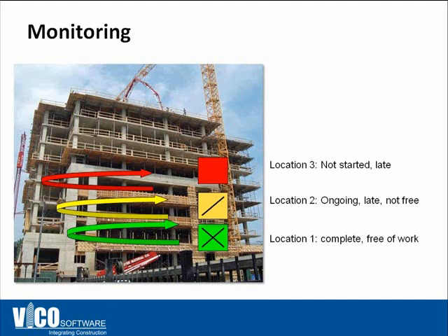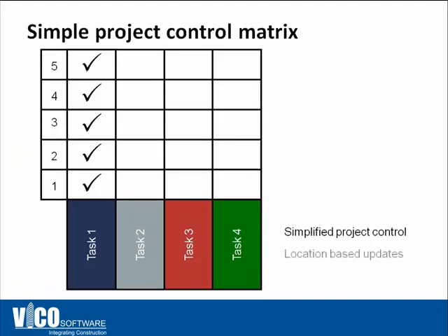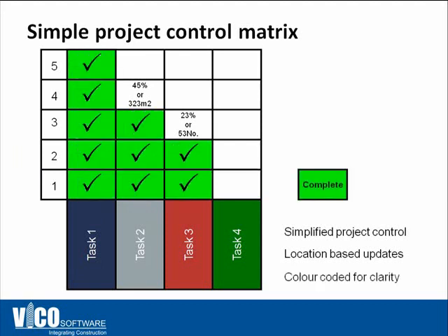So a superintendent would walk the site every Friday with a PE and would have a simple control chart in his hand, printed out. And in that control chart, you'd see the various activities on the bottom, and you'd see the locations on the left side. As they walk the site, they will be able to define what locations are completed, and those are going to turn green automatically.